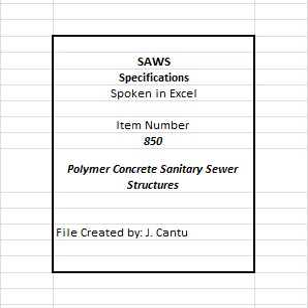850.4 Materials. 1. All fabrication will take place in an all-polymer concrete fabrication facility. 2. All structures shall be watertight and polymer concrete manufacturer must be listed in SAWS Current Approved Products List, APL. 3. Structure covers shall be watertight. Depending upon their specific location, design plans and specifications shall designate locations of vented structures. 4. Every structure cover located in the Edwards Aquifer Recharge Zone shall be watertight.